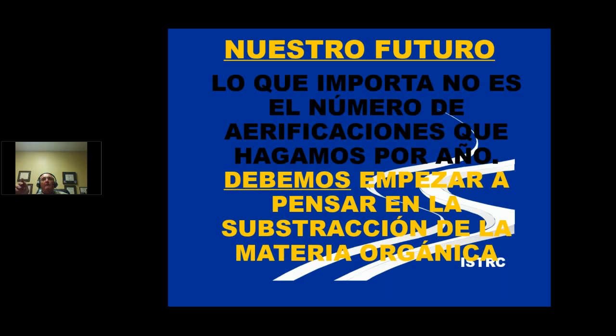Now, from 0.15 millimeter to 0.25 millimeter size, I'd like to have that no more than 15%. And then passing the 0.15 millimeter, I would like nothing more than 3% or less total. So this would be very fine sand, silt, and clay added together. And that will give you a very good top dressing sand. Now, lots of times you can't find that because that's not an easy sand to produce. What you want to try and stay away from as much as possible is the fine end, the material that is actually passing that's smaller than 0.18 millimeter in size.